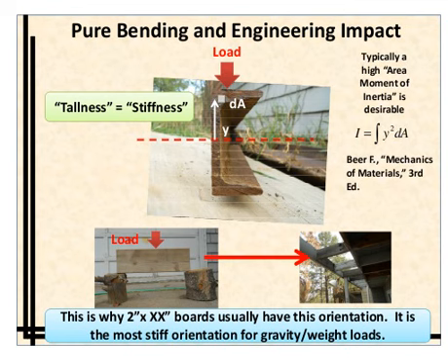And that is why when you look at I-beams or things like this channel here, you'll see a lot of material far away from the center of the beam. And that's because by adding a little bit of material far away from the center of the beam, they're significantly increasing the area moment of inertia, but it's not taking as much material, which would cost more money, and it's not taking as much material that would add weight. And so you're getting a structure that's lighter and cheaper and still has good stiffness properties.